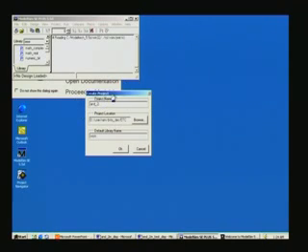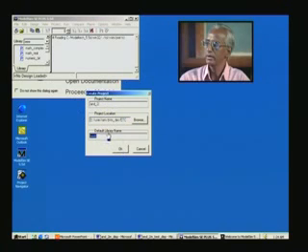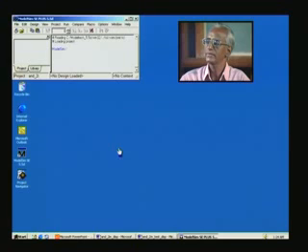So we'll give that itself as a project name. And there is one more thing, we have a library here. This one you have to create a work directory, and you have to work in that one, not in IEEE. Otherwise some platform dependent files will be overwritten. That's not a desirable thing. So you always use a work directory as such. Just say OK. Let us see what is happening.